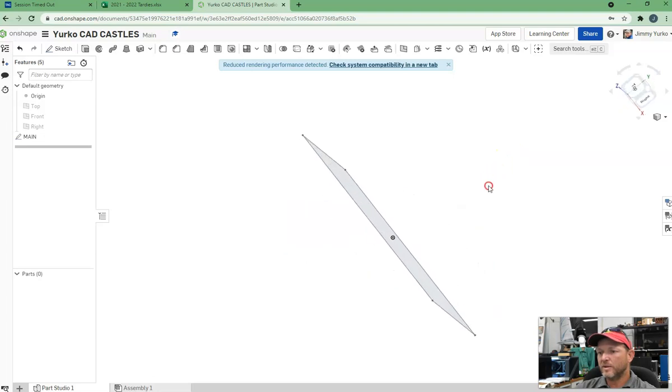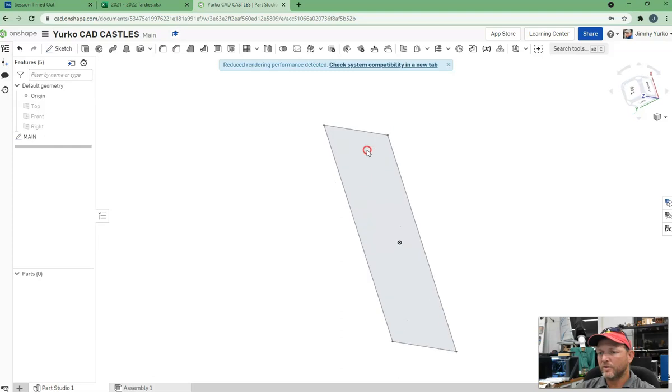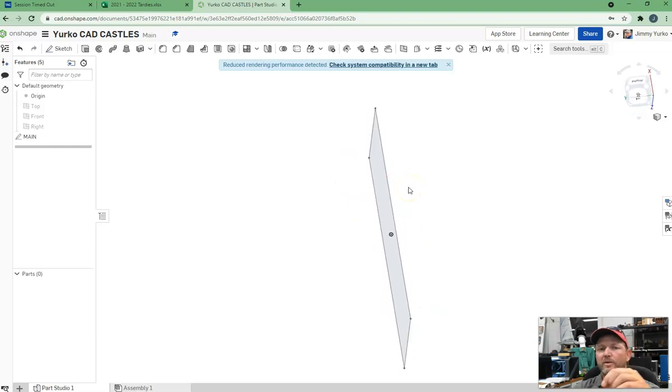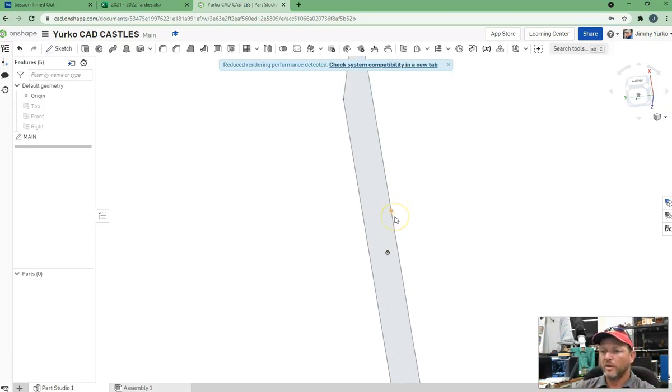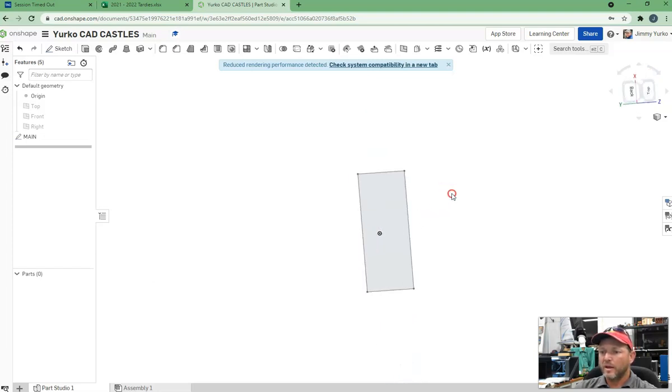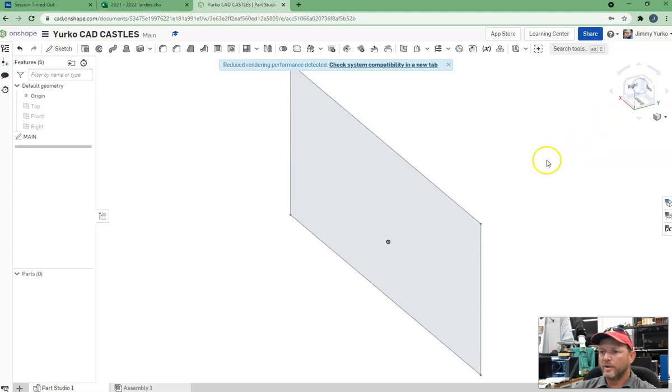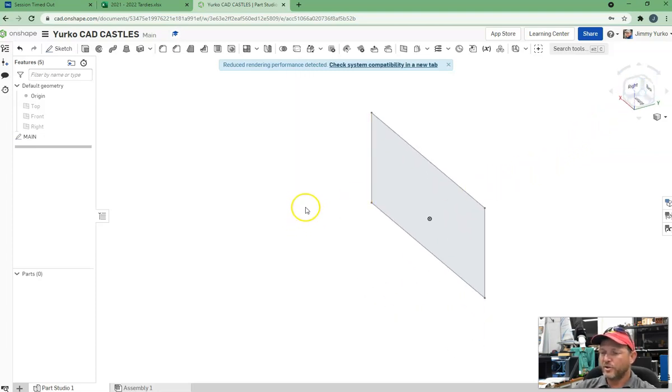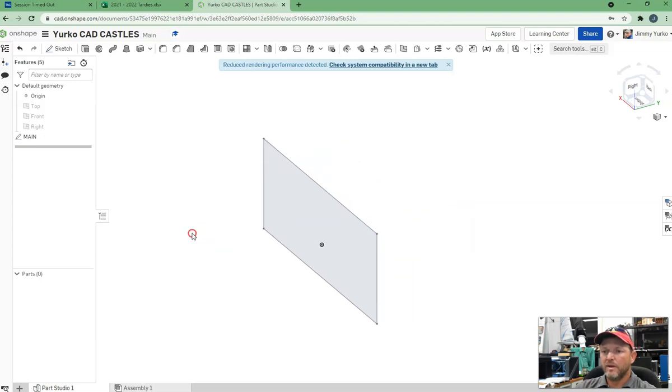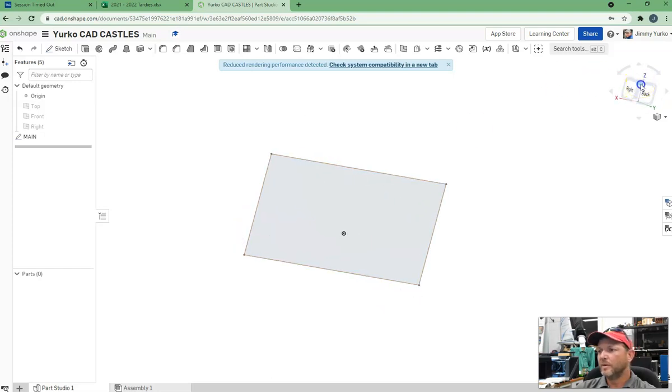It's in 3D space. Now if you're wondering how I'm getting the space to rotate so freely, easily, I'm holding onto the right mouse button on my mouse, and the scroll wheel on the mouse allows me to zoom in and out. As well, the scroll wheel, if I push down on it, click on it like it's a button, I can use that to pan the camera around to move things in 3D space.